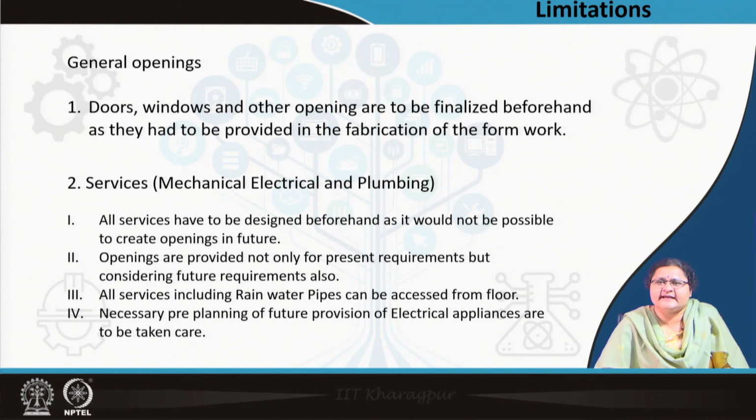Even staircases can come as a precast item. So, the entire flights of the staircase, the risers and the treads can come precast to site. So, there you have to remember how many treads, and how you have to calculate the dimension, and keep that space enough so that it gets assembled with the beam column system. Then only you can achieve speedy construction.